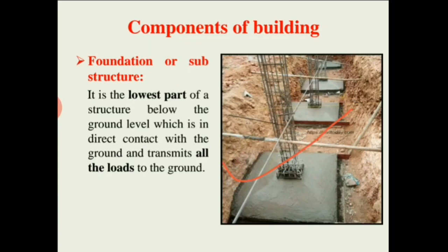So foundation is a very important part of a building. It is the lower portion of the building, usually constructed below the ground level, which transmits the load of the superstructure to the subsoil.